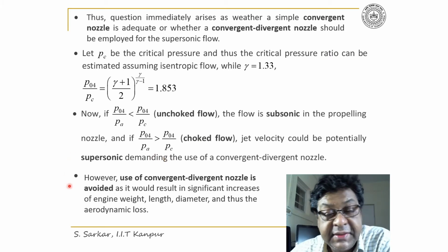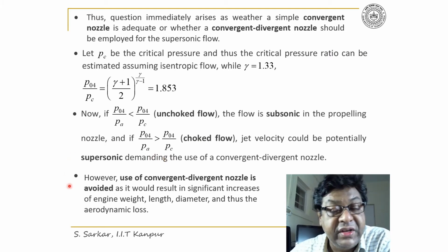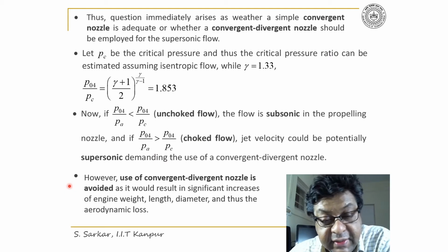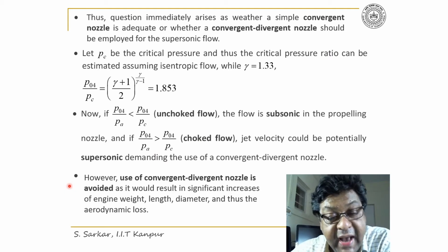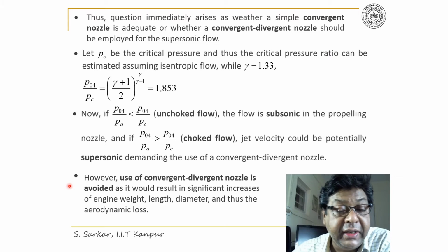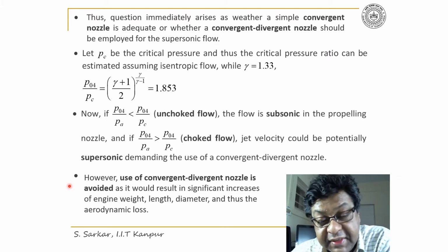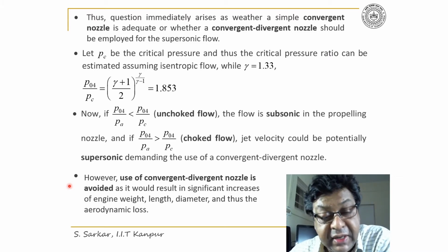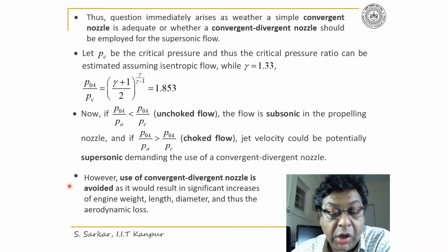However, the use of a convergent divergent nozzle is avoided as it would result in a significant increase of engine weight, length, diameter, and thus aerodynamic loss.